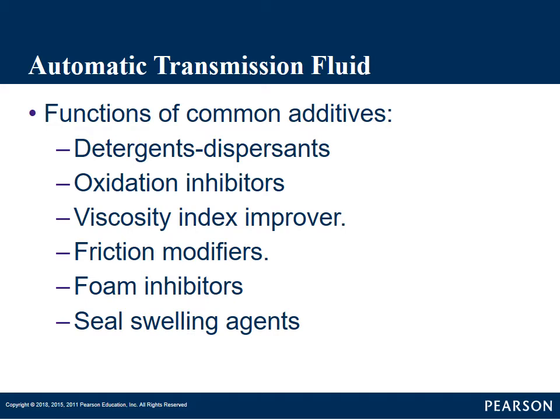And this is a big deal when we're talking about valves, because once we start getting into the valves in a transmission and the valve body, very tight clearances, very important that we keep these valves and the valve body clean, or we're not going to get proper shifting out of the transmission.